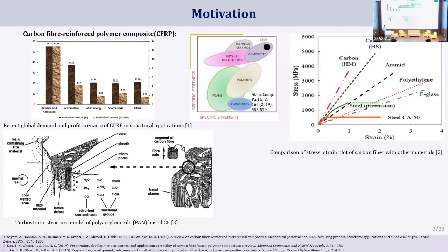If you see that figure, at the bottom left corner, you could see the graphite structure. The basal planes of the graphite structure are present at the surface of the carbon fiber, and this is chemically inactive in nature. So this cannot bond with the epoxies easily. So the material fails at this region because there is a lack of chemical bonding here.